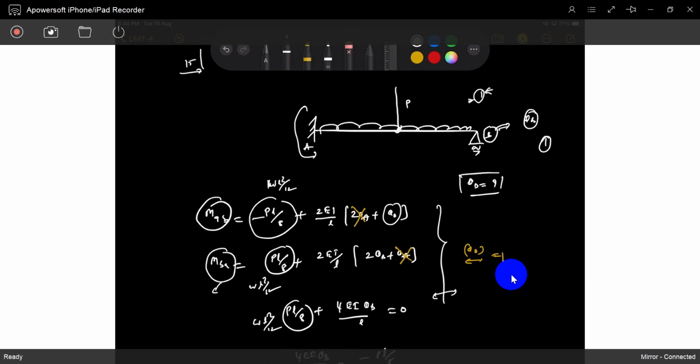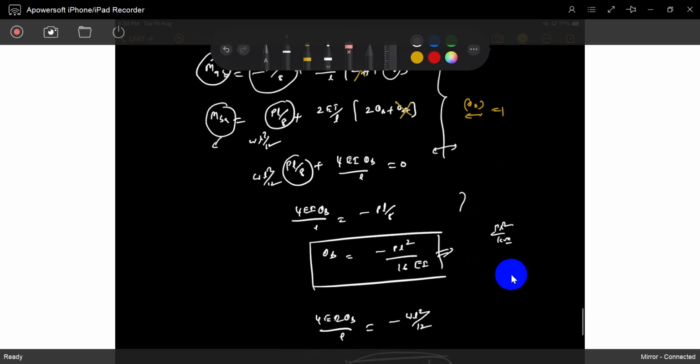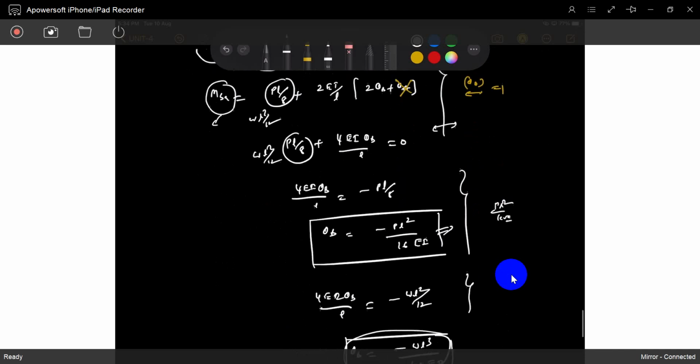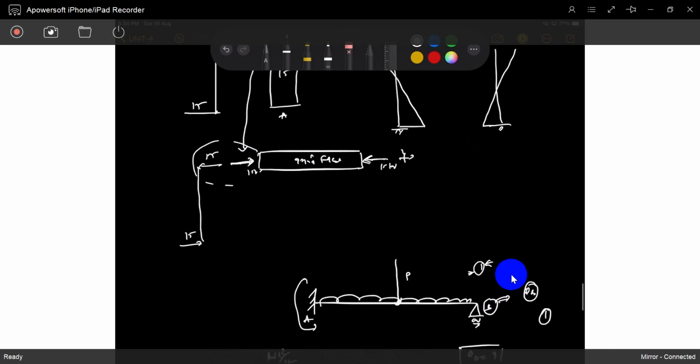So we skip those problems. We already solved problems of at least 2 indeterminacy. But you can use this and you can get any slopes. Easy, very, very easy way. You don't have to remember those propped cantilever moments. You can solve it within 1 minute and you will get the answers. You can use it in GATE problems or very objective problems.